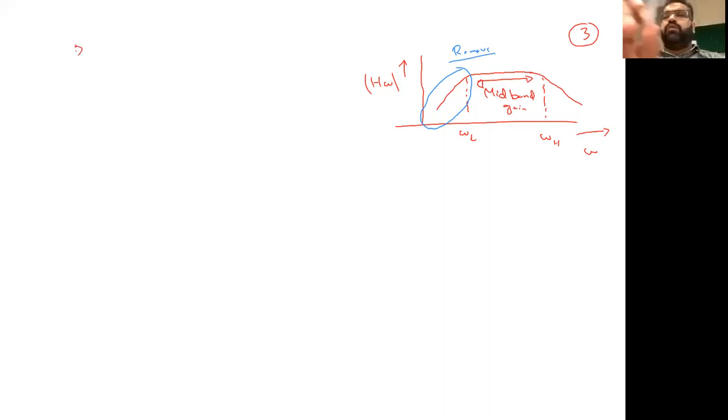First and the basic thing is that C in is a DC blocking capacitance. Sometimes, in low frequency applications, I don't want any amplification of the DC side. DC comes because of motion artifact, or because of some errors, so we want to get rid of the DC value. To get rid of DC, I should have high pass filter characteristics at 0.1 hertz or whatever the related frequency is. Something similar to audio applications: I don't want frequencies below 20 hertz to be amplified, or, for example, frequencies below 100 hertz to be amplified.